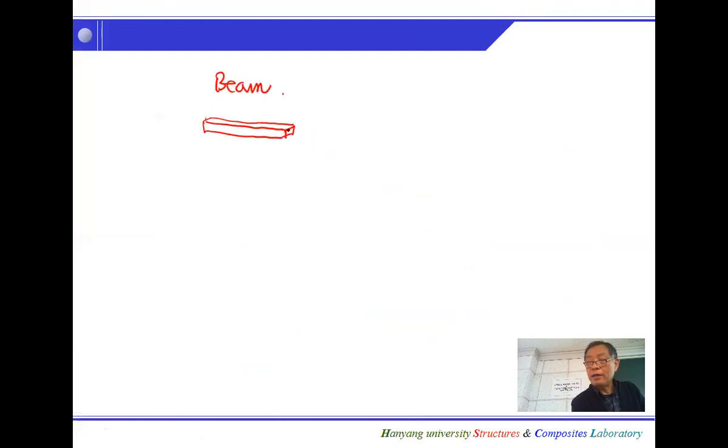This one can be either extension or bending, I mean the curvatures. So any strain is a function of Z. Z is from here. Any function of Z now can be epsilon 0, a constant term, plus Z times K. What is K? Curvature, right?